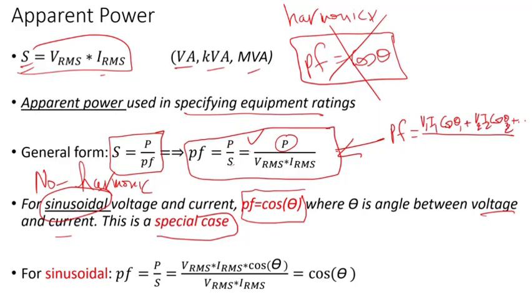How many terms do you have? This here is the fundamental frequency, or harmonic order is 1. So if you have a 60 hertz system, it's 1 times 60, which is just the fundamental frequency. This is the second order harmonic, H is equal to 2. If you have 60 hertz frequency, then it's 2 times 60 is 120. So this signal would be at 120 hertz.